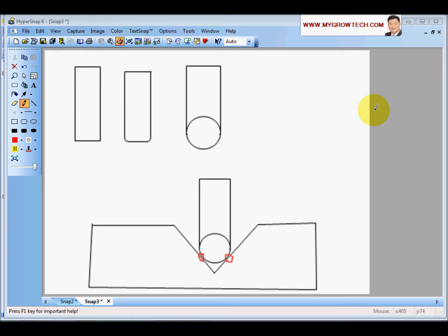Before we touch on the pencils, I'm going to explain how the pencil process detects the corners. So in the penciling process, Cimatron is using the cutter radius touching point here. Okay, the cutter radius, the tangent touching point. So if you have a ball and the radius of the ball is smaller than the corners, then you have two touching points. And from this, Cimatron can know where the corner to machine is.